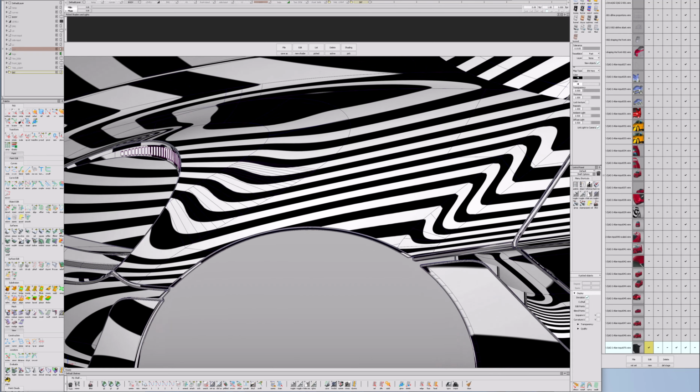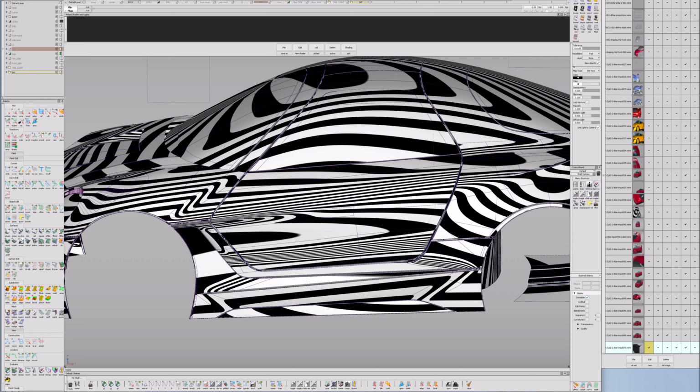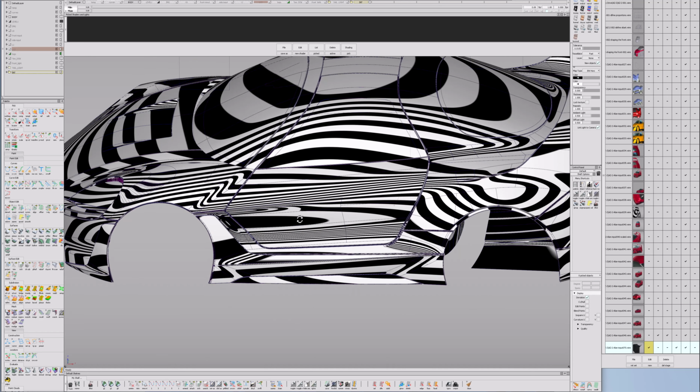I don't care now. I know I can do it in A-class, and I can spend a lot of time doing it on the whole car. But why should I do this just for a render? So you always should know the purpose of the model. If the purpose is only a render, you can cheat as hell. You can do whatever you want. Even sometimes tangent is okay. You shouldn't do curvature, G2 or anything.